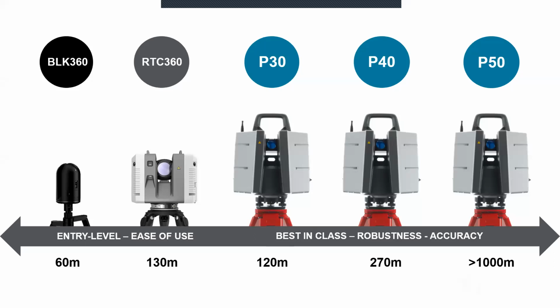Because if you are constructing a 100 meter or 500 meter high building, and a 1 mm error starts at the first floor, this will be a few centimeters by the time you reach 500 meters. So it's important to understand all those smaller errors, because those can be big disasters when the whole building is ready.